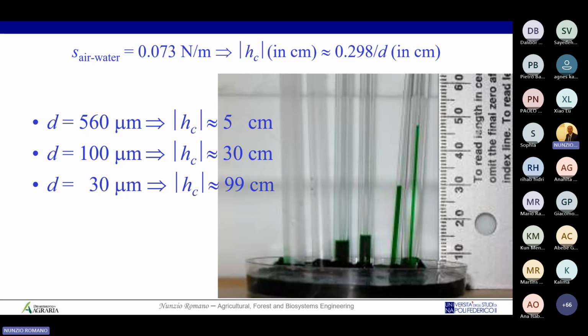So this is why you can get a capillary rise above the groundwater level even more than 1 meter, even 5, even 10 meters. With this very simple exercise, now you can understand the relationship between the capillary rise and the porosity of the soil you are dealing with.